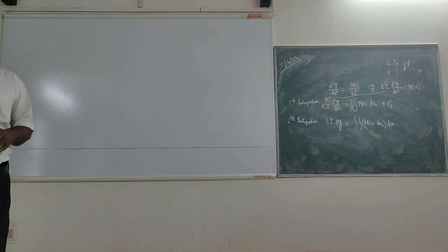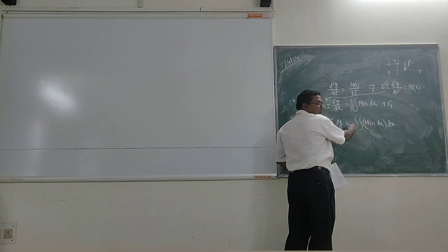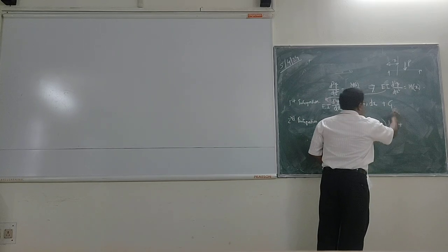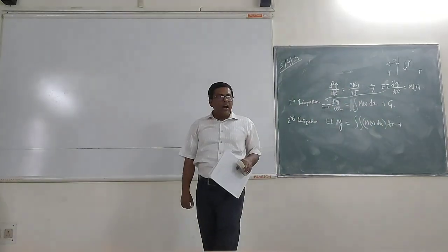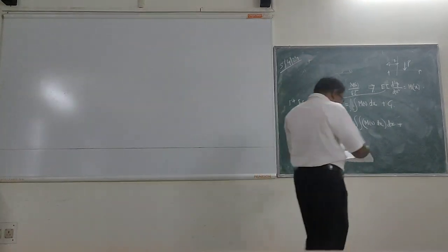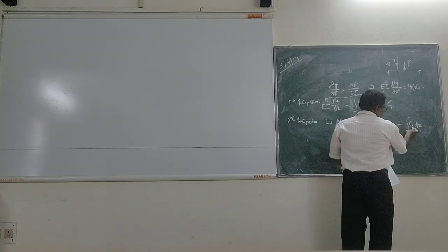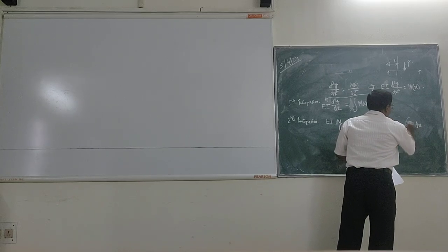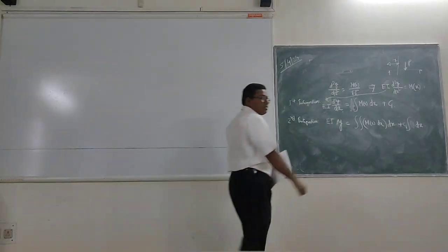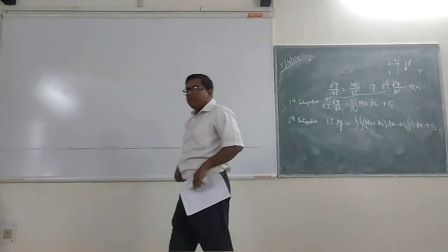The integral of M(x) dx was initial. Now this dx is going on the other side, and there is another integration coming in. So M(x) dx, and then another dx. And then C1 is a constant term, so there will be integration of C1 also. C1 will be integrated and written as C1 dx, where I can bring this C1 outside, so I can write C1 times the integral of dx, plus there will be another constant of integration coming. Have you understood?